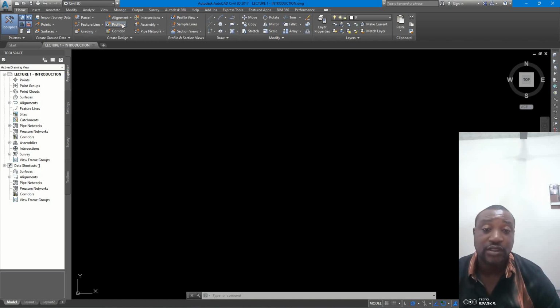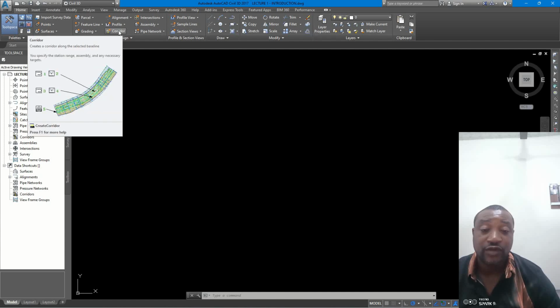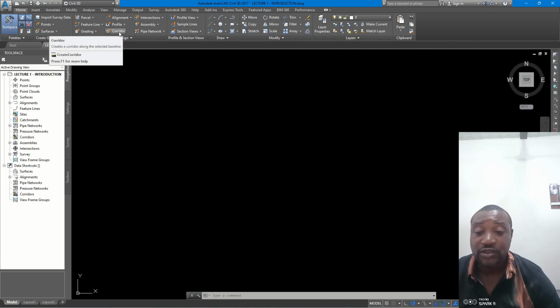While the corridor is the template showing the thickness of your asphalt, in structures showing the thickness of the stone base, the thickness of the fill material. Even if there's a shoulder, there are some conditional assemblies that you'll be applying here, which implement cut and fills and daylight, benching, and so many more is found from this angle.